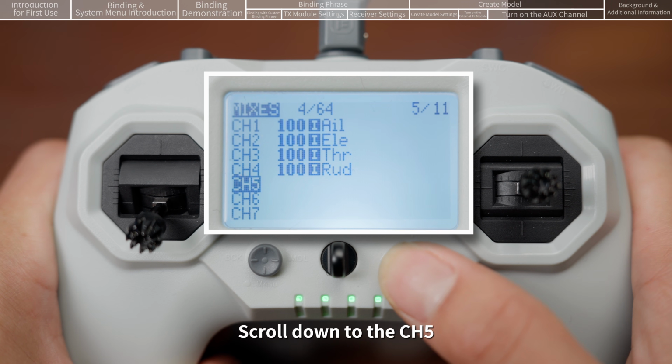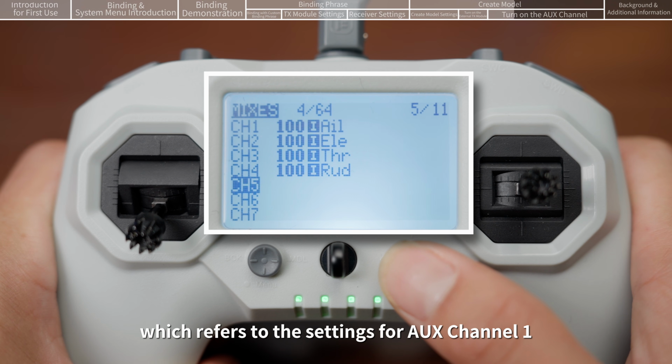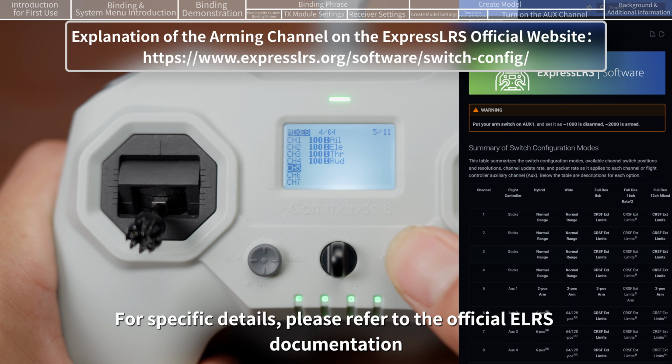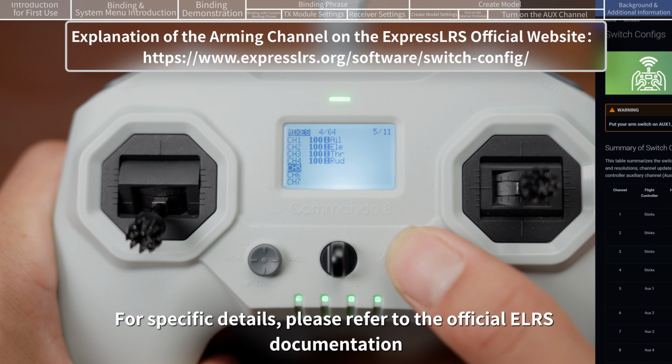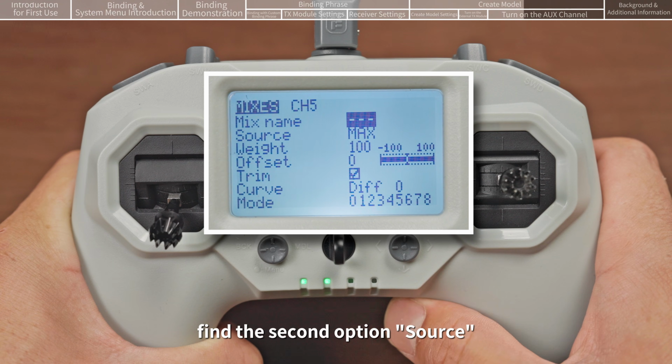Scroll down to the CH5. CH5 is typically assigned to AUX1, which refers to the settings for AUX channel 1. It is usually set to the ARM mode function. For specific details, please refer to the official ELRS documentation. Short press the right 5-axis button. Enter the menu. Find the second option, Source.